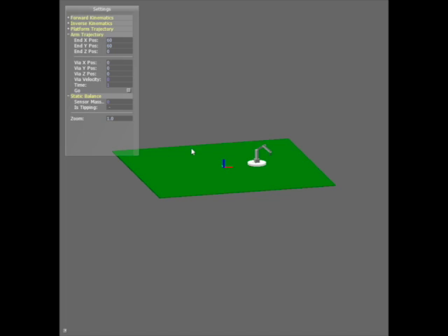When we set it to 0, we can see that there is no mass and there is absolutely no risk of tipping. When we set it to 500 grams, we can see that there is still no risk of tipping for the robot. We can see that once we have set it to 700 grams, there is a risk of tipping, which is shown here.